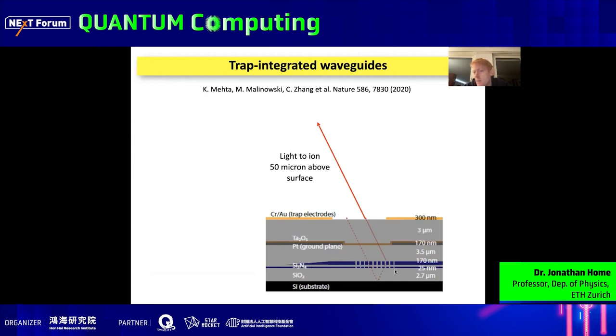And then when we get to the place where we want to deliver light out of the chip, we have a grating which diffracts the light and focuses it above the surface. This is all done in a fairly standard foundry, on a silicon substrate. One thing to note is that this grating doesn't just take light out of the chip directly, but also reflects some light off this bottom surface in order to deliver it.